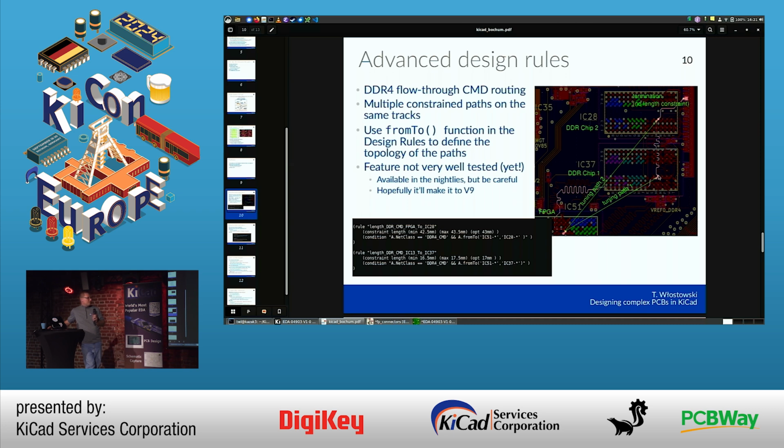We want the electrical distance from here to here to be constrained, and also from here to there. I would not like to constrain this part because there are stubs that also have non-zero lengths, right? All I care about is the distance between a driver pin and the target pin. Well, there is also a small stub here for the 50 ohm termination, but its length is irrelevant in this case. So how do we do it?